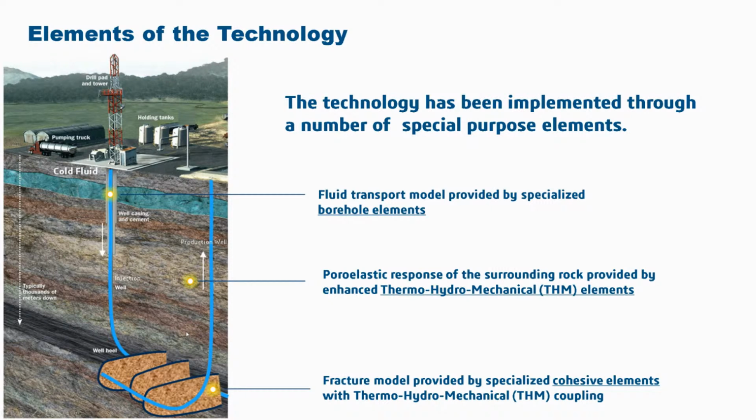We have also developed special models to capture the fracture of the reservoir rock in case of enhanced geothermal systems. And these fracture models are provided by specialized cohesive elements, and these cohesive elements also have thermo-hydromechanical coupling. In what follows, I'll give you examples of each of these technologies and how these technologies can be combined together in different ways to solve different types of problems.